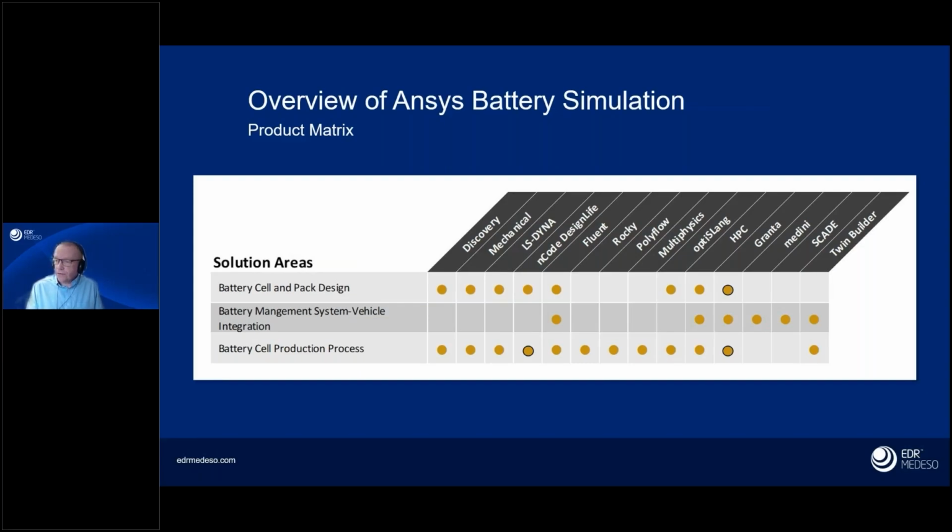Fluent CFD scales incredibly well on GPU and CPU. LS-DYNA will scale very well on multiple cores of CPU. And Ansys Mechanical, again, scales very well on CPU. And in fact, the 2025 release is starting to get in some really powerful GPU scaling capabilities as well. So I would expect that if you're considering this as a simulation you need to do, then you're going to have some HPC.